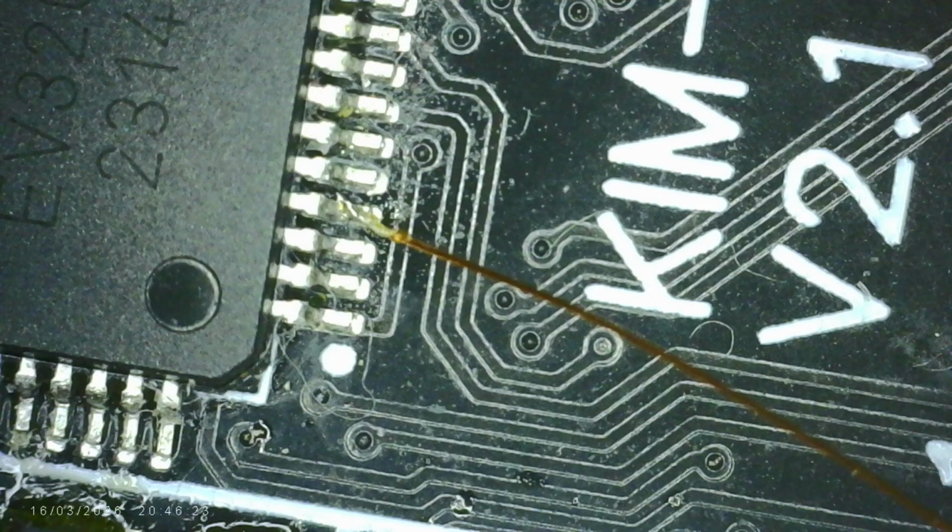I found the smallest enamel copper wire I've got, which is 0.1mm in diameter. And amazingly, on my first try, I managed to get it to solder onto port G pin 6. That's on pin 1, 2, 3, 4. Then the other end I managed to scrape clear and tin a bit so I could connect it to the logic analyzer. So now I could turn an output on and off to sample what's going on within the processor.